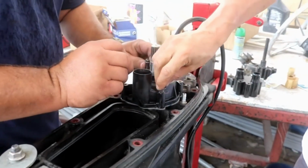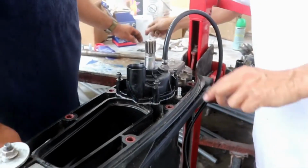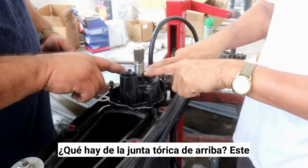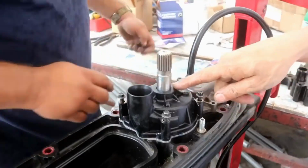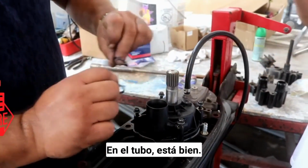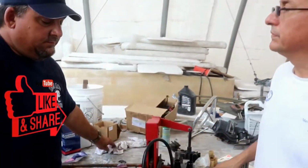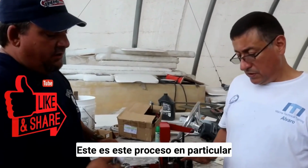Put the bolts and apply the torque in diagonal. And what about the O-ring on top? This one actually has it inside. And then the O-ring that's on the shaft will actually go in here in the tube. In the tubes, okay. And you have to put grease on these as well. In both of them. That's simple. That's the process on this particular outboard.